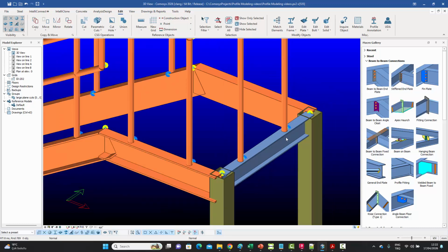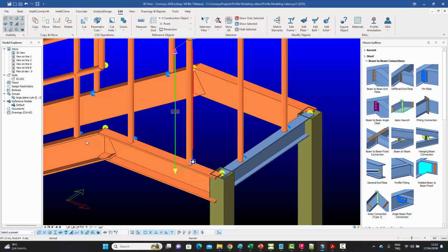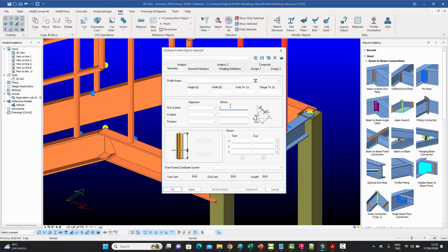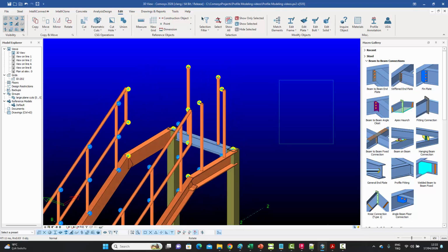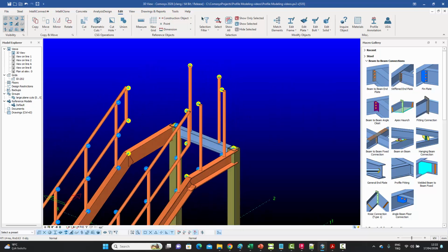The only difference is that the other posts were offsetted, if you remember, 40 millimeters because of the stringer being entered from the backside. But this one is an I-beam which is entered middle, so we will need to basically remove that offset for these two. Make this 0 like that. And now we have the 4 posts correctly entered as well.